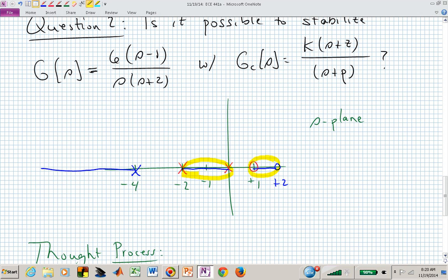Because we start at poles, this one is going right, this one is going left, and they can't just stay and have a party in the middle, can they? Once they meet, what happens? They break away. So there's a breakaway between the origin and -2.